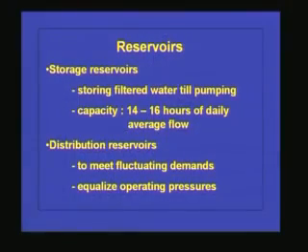Again, in any water distribution network, we not only have the pipes, but we also have reservoirs. There are two types of reservoirs. One is a storage reservoir and the other is a distribution reservoir. A storage reservoir is meant to store the filtered water that is coming from the treatment plant.